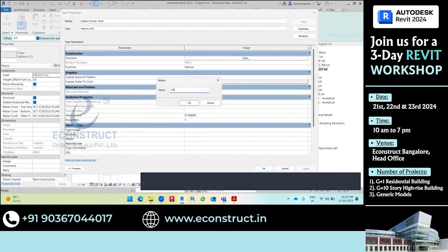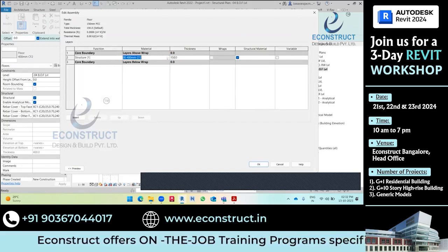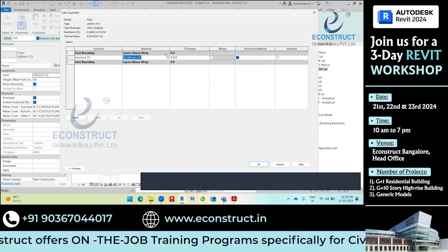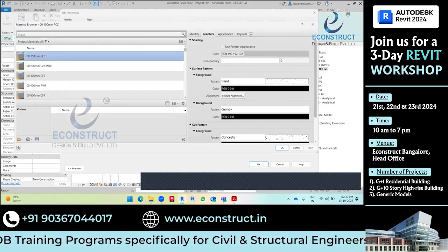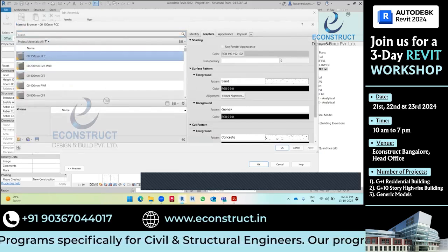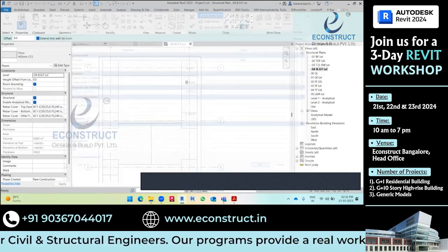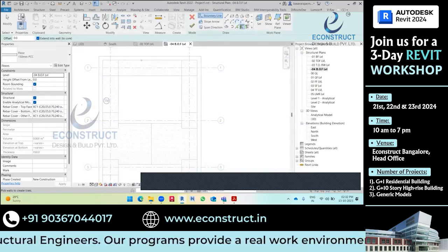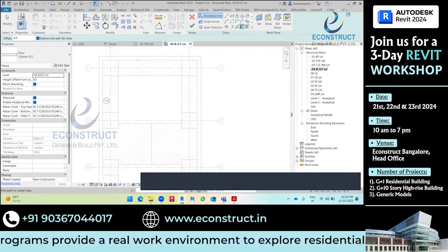Okay, like 150 mm PCC. Okay, go to edit. Change the thickness to 150 mm and create one new material for the PCC. Select any one. Yesterday we have already created one material, 150 mm PCC, so I will select that one. Click on OK. Okay. So I will take some 3 inch or 75 mm extra from this edge of the footing.